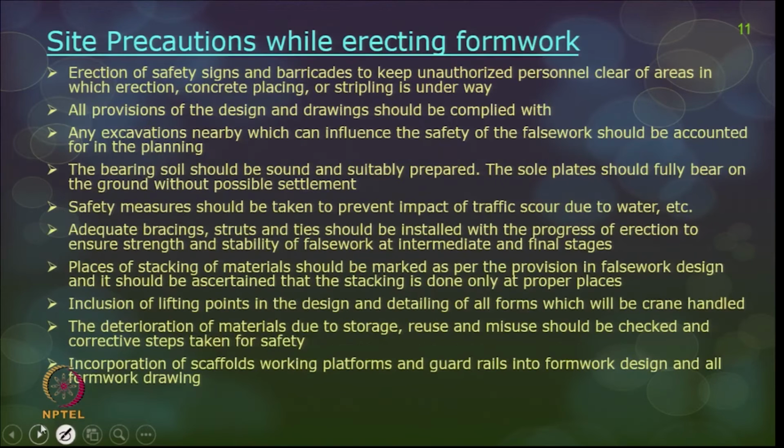Some more site precautions while erecting formwork. There should be proper safety signs and barricades to prevent unauthorized people from entering the site. Also, while you are placing your formworks, pouring in concrete, or stripping off the formwork, during all these operations there should be safety signs and barricades erected. All provisions of the design and drawings should be complied with, and as I said already, it should not be misunderstood since it is a temporary structure.